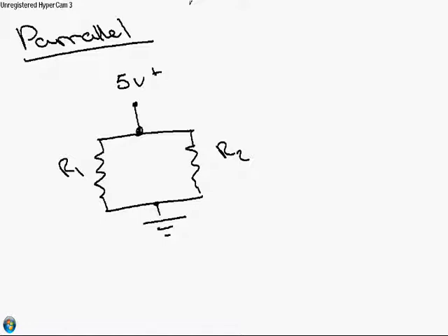But if you're doing some really advanced stuff, I've done stuff with transistors where I've needed 28 point some odd ohms of resistance, and they don't make them in fractions of ohms, or at least I couldn't find them. So coming back to parallel and series is very useful.